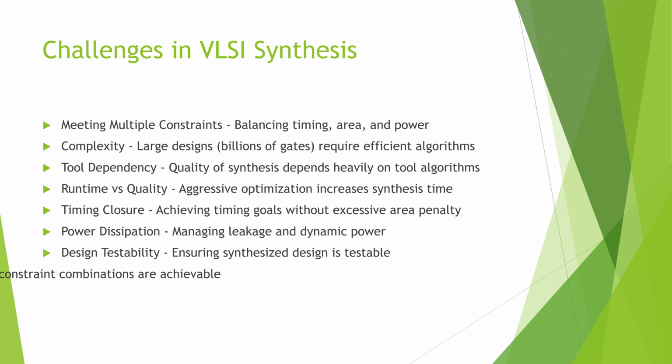Now, let us mention some challenges in VLSI synthesis. First, balancing multiple constraints like timing, power, and area is hard. Second, large designs with millions or billions of gates require very efficient algorithms and a lot of memory and time. Third, timing closure is often difficult, especially at advanced process nodes. Fourth, power dissipation, both dynamic and leakage, must be controlled. Fifth, design must remain testable, so DFT requirements must be satisfied. And sometimes, certain combinations of constraints are simply not achievable.